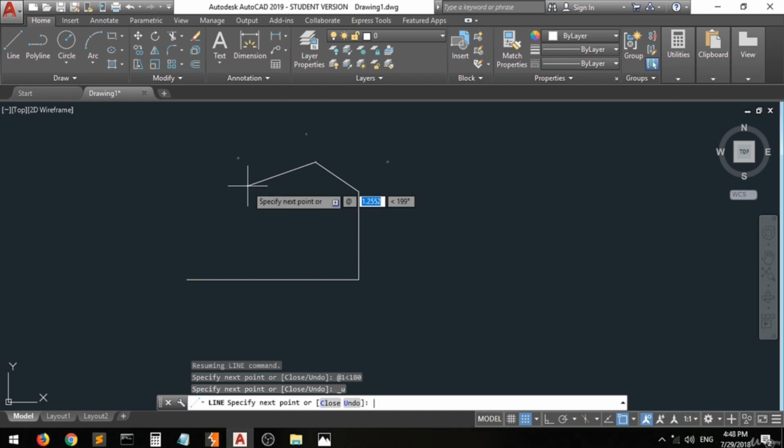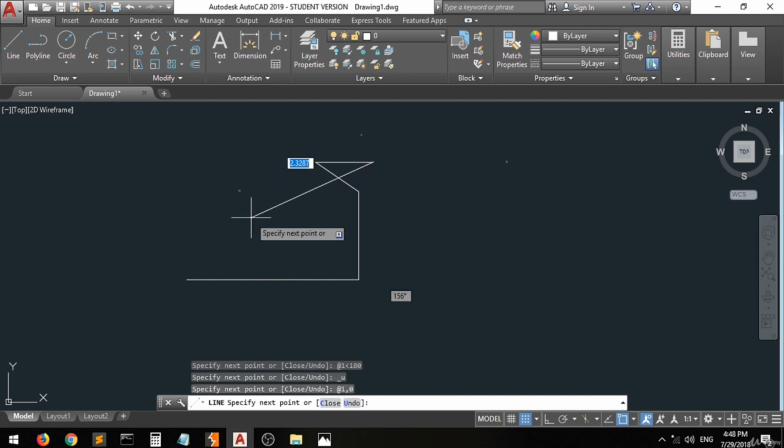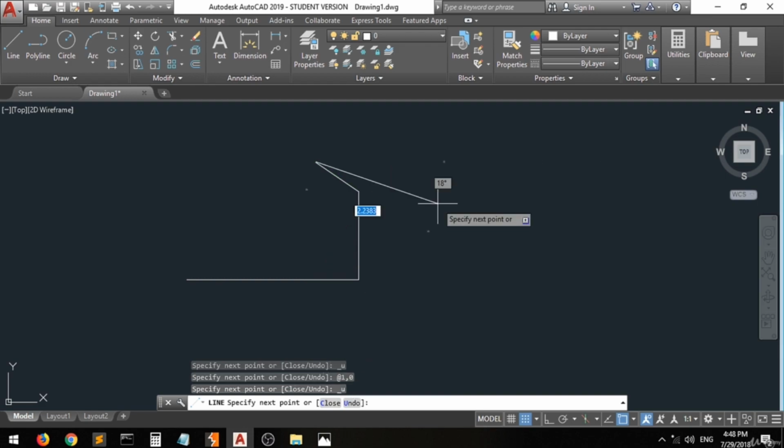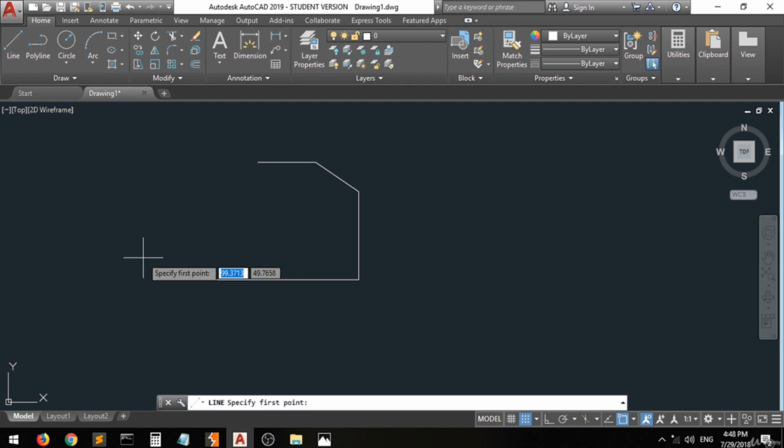You have to type what is the length, or what is the x coordinate of this line? It will be 1 slash. In the y-axis, we're not moving, so we will type 0. And now enter. No, we have entered it wrong. Why? Because we are moving -1, not moving 1 as we did here. This has to be at -1 slash 0, right? So Control Z again, and let's type at -1 slash 0, okay. And now it's created. So now press enter to end the session.